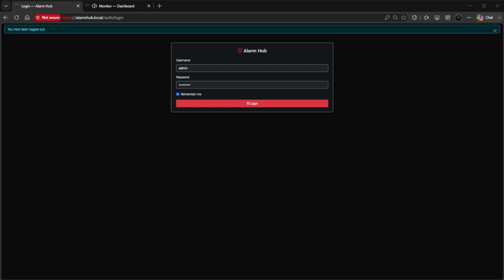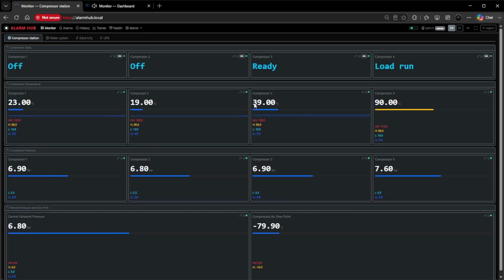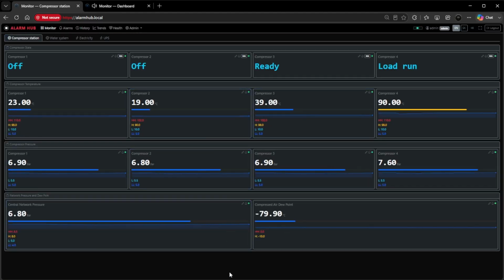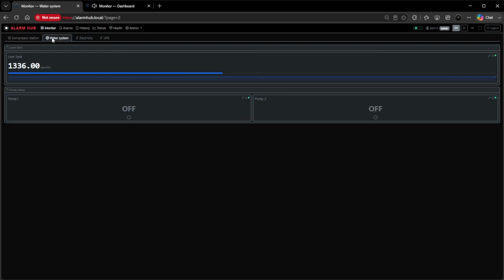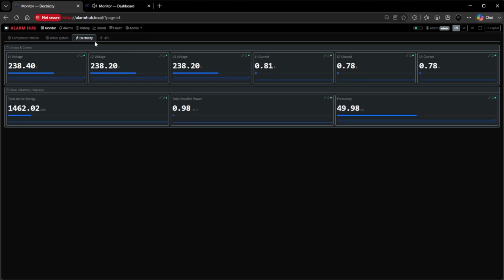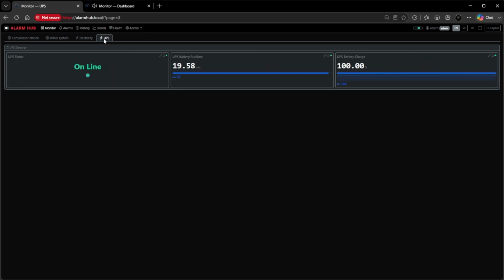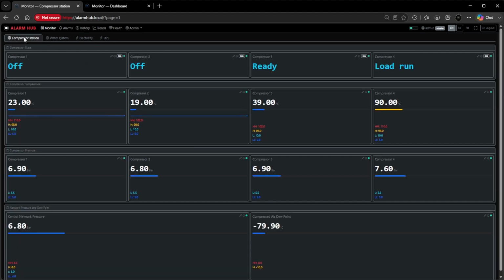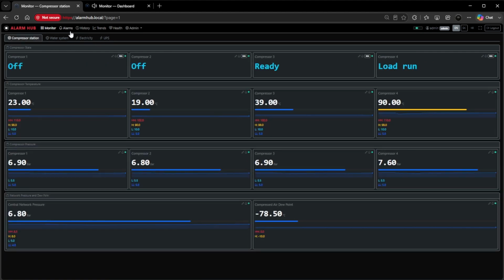This is the Industrial Alarm and Monitor Hub, one place to watch the values that matter across an entire plant. Before anything else, this system only monitors and alarms. It never controls. It doesn't start a motor, doesn't flip a valve, doesn't write anything back to a machine. It reads, it evaluates, and it warns. That's deliberate. A monitoring layer should never be able to become the thing that breaks the process it's watching.